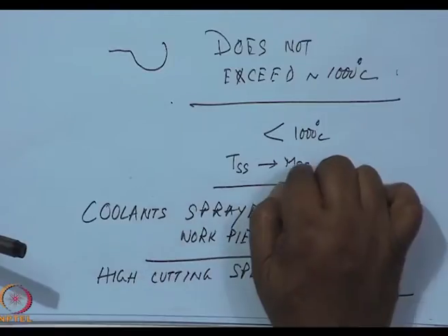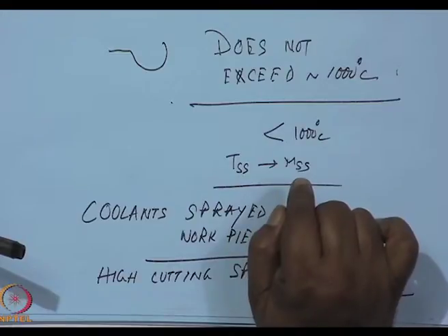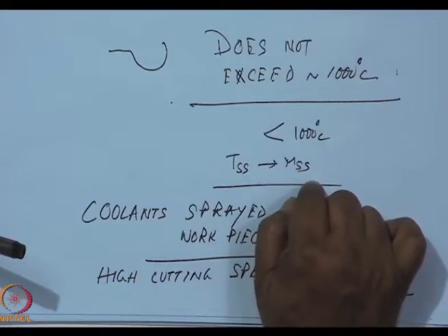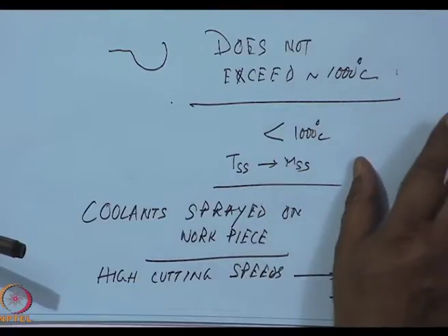And so, this requires a balance with the phase transformation temperature of the maraging steel, if there is a phase transformation on being cooled, because you cannot allow the temperature at the cutting tip of the partially stabilized zirconia to exceed 1000 or 1050 degrees centigrade.